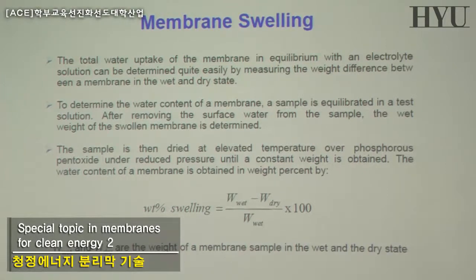For example, if it's put into water for 1 day, after 1 day you can take it out and blot the surface water of your membrane with some Kimwipe and measure the weight, which contains the dry weight of the membrane plus the water that was contained during that one day.